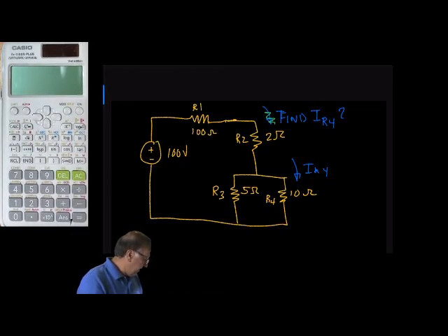There are two general approaches to this problem. We could determine a voltage across R4 using Ohm's law. We could also use the current right here, and then use the current divider rule. We could also measure the voltage across R3 as such.